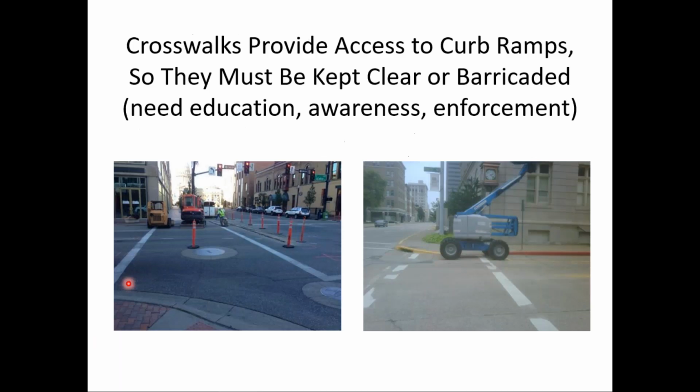Crosswalks provide access to curb ramps, which are considered the basic element of accessibility, so they need to be kept clear or barricaded and a detour route identified. And so that may take some education, awareness, enforcement on the part of the contractor or construction personnel.